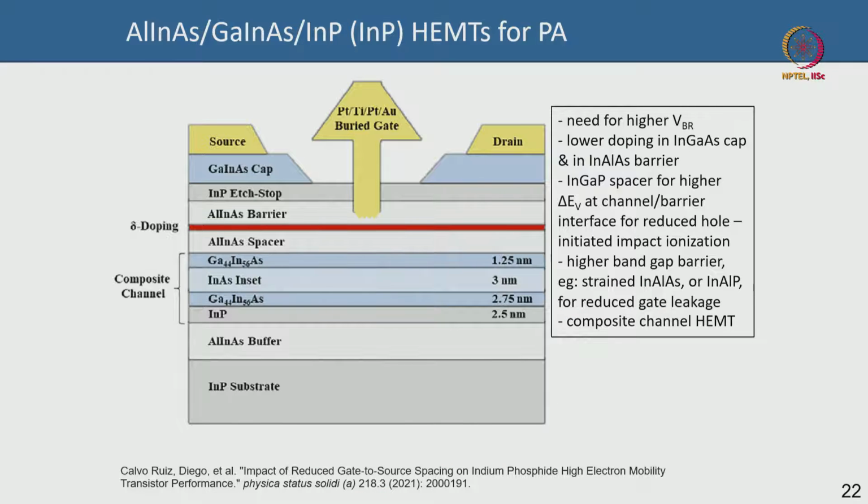For power amplifier, these had not been so attractive because of a lower breakdown voltage, but people are smart, so people have come out with techniques to improve the breakdown voltage. So to get a higher breakdown voltage for power amplifier for indium phosphide based HEMTs, lattice matched or pseudomorphic, doesn't matter, there are different techniques. One is the double recess, which is a very common technique. People can put field plate around it, which is not shown here, okay, and then the InGaAs cap,